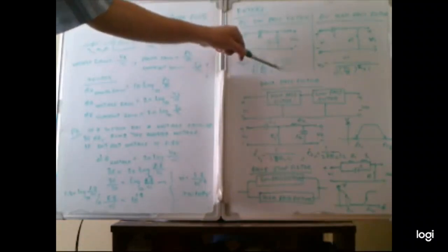We also utilize filters in the circuit. A filter blocks high frequency, harmonic frequency, and impurity. A low pass filter, connected like this, means only low frequencies can pass through. The output voltage V0 is Vi divided by the square root of the quantity ωRC squared plus 1.